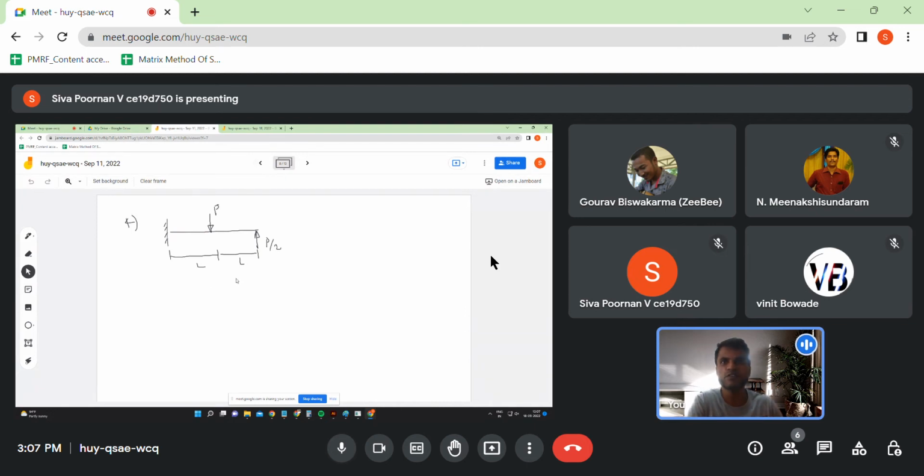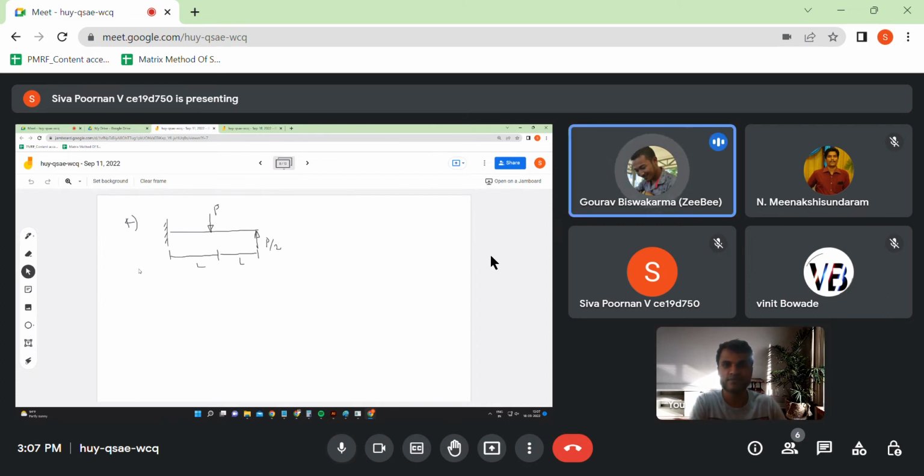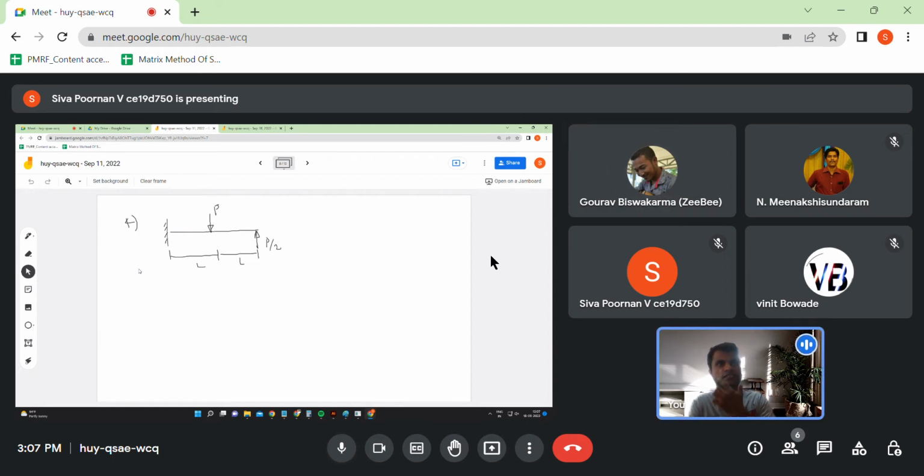So in these, maybe we can finish these questions and then go back to basics of FEM, right? Fine. So, what is the deflected shape that you guess for this problem, and what is the shear force and bending moment? At the fixed end, the slope would be zero. At the far end, there will be a slope. Before, yes, at the fixed ends we anyway will have the slope as zero. But what is the shear force and bending moment that you would expect?